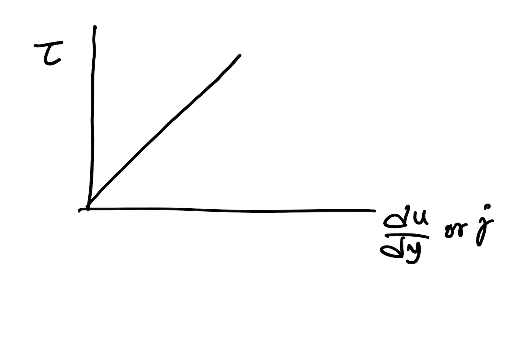Okay. The last aspect about viscosity that we should understand is that I told you that if you have shear stress plotted as a function of the strain rate, if you have a straight line, the slope of that straight line is what you will calculate as the viscosity of the fluid.